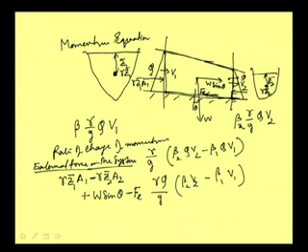Well, we may avoid this term also. The forces on the system are like this, and then this should be equal to the change of momentum. So, our equation that we can write now is Q gamma by g, then beta2 V2 minus beta1 V1, that is the rate of change of momentum.